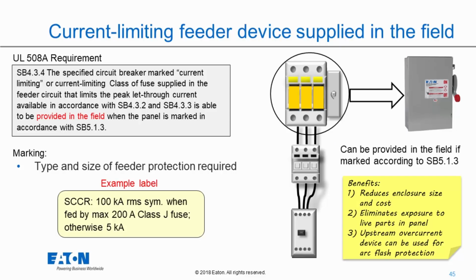But a lot of people do it for arc flash and shock reasons, because as soon as you turn off that main, if that main is outside of the panel, then you have nothing live when you open the door. So a lot of people, for those arc flash and shock reasons, really like to use this. It's totally allowed, and we want to be able to use that upstream fuse to help us increase our SCCR when we can, and that's fine.